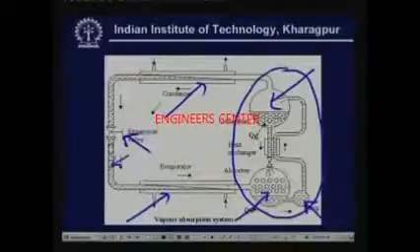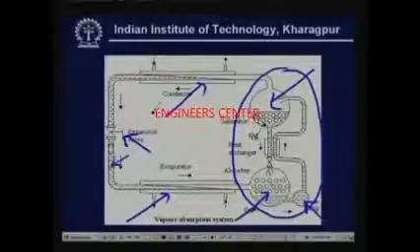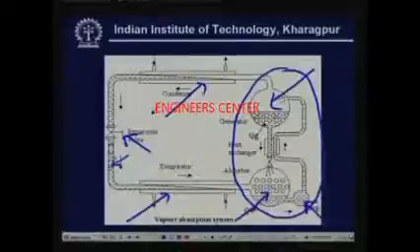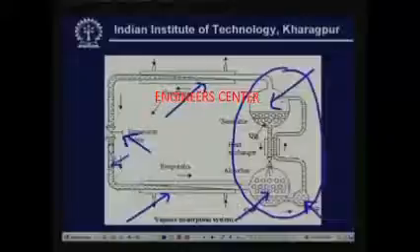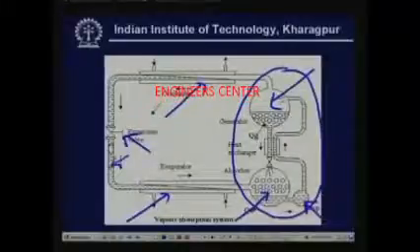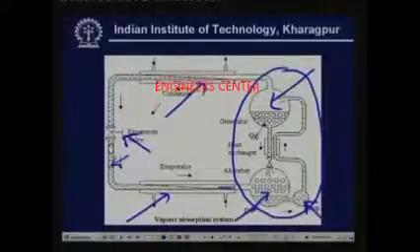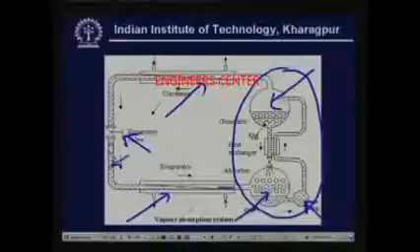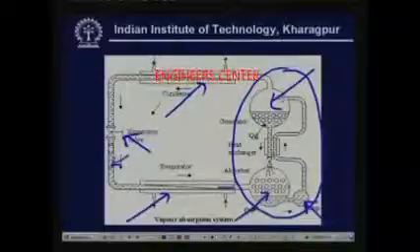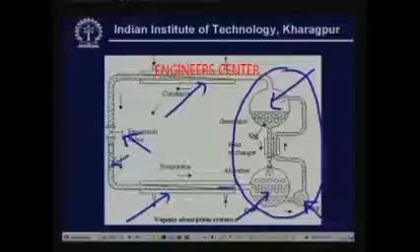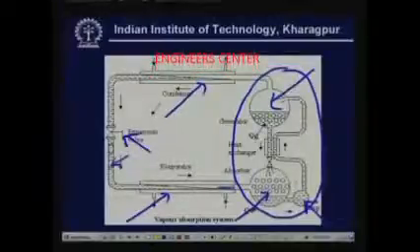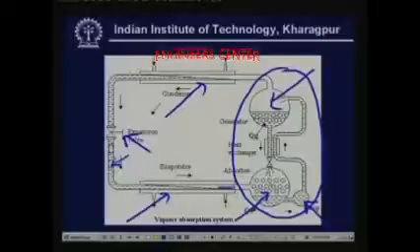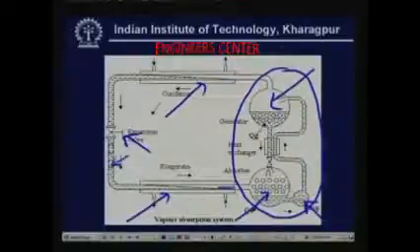Now what happens is, when this vapor comes in contact with the absorbent in this absorber, since the absorbent has high affinity for water, it absorbs the water vapor. That means this absorbent continuously draws the water vapor from the evaporator. So you have continuous generation and continuous withdrawal of the water vapor from the evaporator. This is like the suction of a mechanical compressor. Then, as the absorbent absorbs water vapor, it becomes strong in refrigerant.